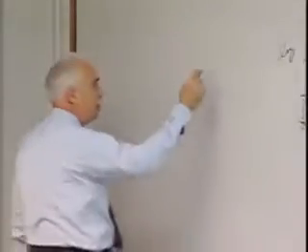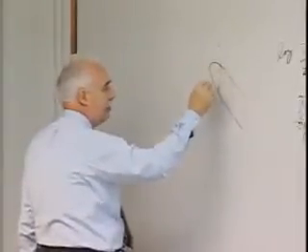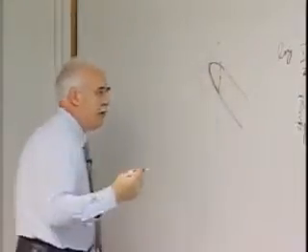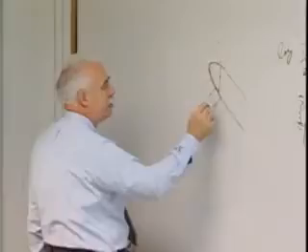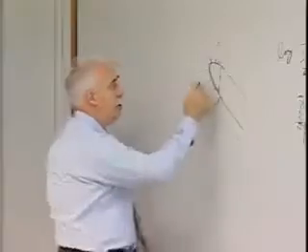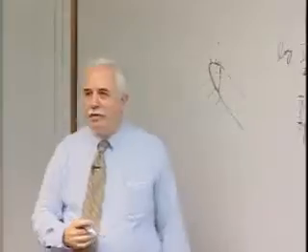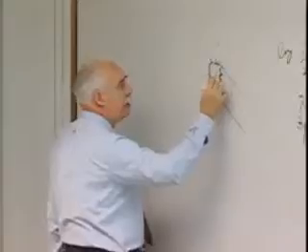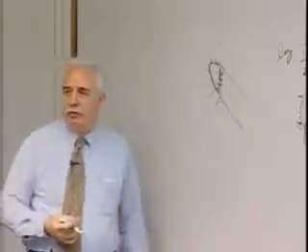Just picture a two-dimensional airfoil at angle of attack, and the carbon section, if you want, covers from here to here. Now if I look at the heating distribution, here the heating is quite high, still high over here, still high over here, still high over here. Boy, it drops off very, very quickly over here. Well, if I can radiate this energy over here, this basically becomes a uniform temperature oven, first order. And the insulation is back here, to keep the lower temperature structure from getting too hot.